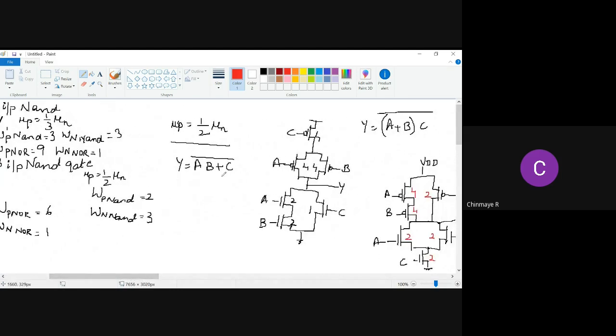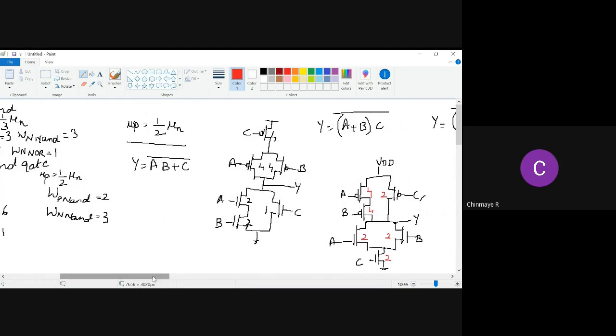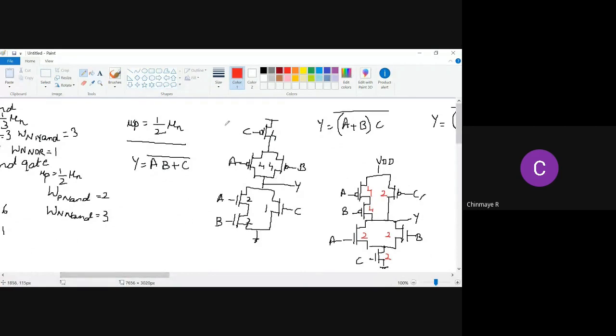Next, what we did is to size some of the complex circuits, right? Some of the complex circuits, like, I mean, you cannot exactly call this complex though. So AB plus C the whole bar, right? So what is this basically? Have we studied this earlier? What do you call this? You have an AND operation, you have an OR operation, you have an invert operation. So you call this an AND-OR-Invert, yes, AND-OR-Invert, based on the inputs here, right?